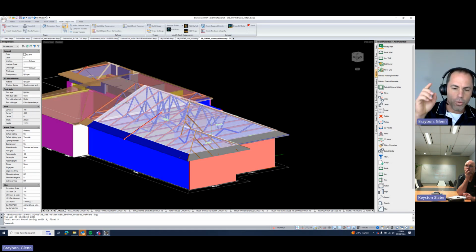So the reason that the INS punch came in, you've got that option ticked in your detailing options to put an internal bottom plate web notch next to openings. Oh, really? Yeah. So when your bottom plates come out, there's going to be a notch at every opening. We've had that turned off. We haven't used that for a long time. Really? That job you sent through had that turned on? Okay. Far out. That potentially might save a few things. Okay, so that was turned on.